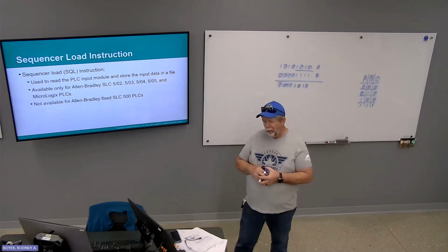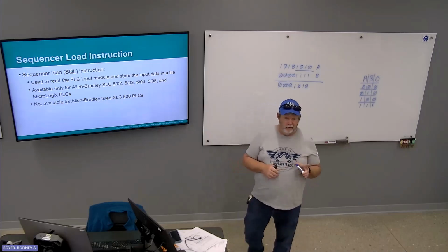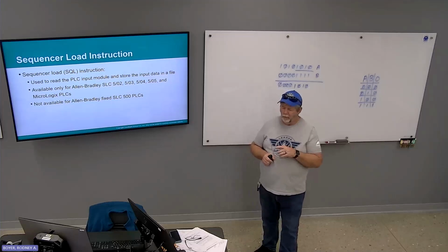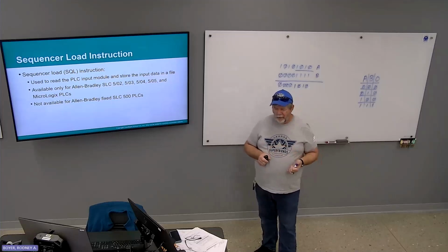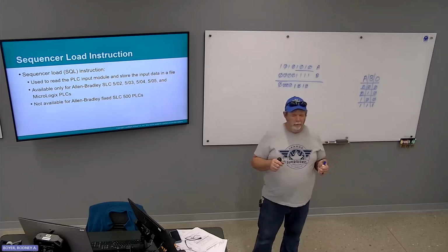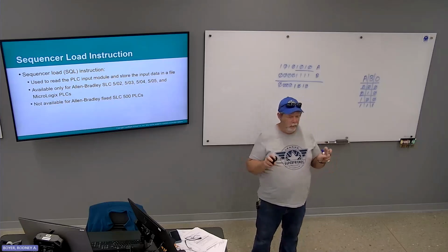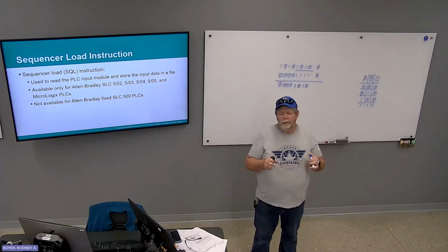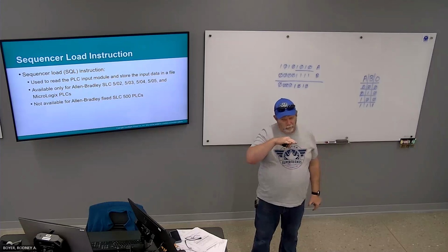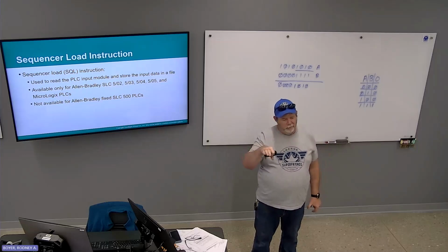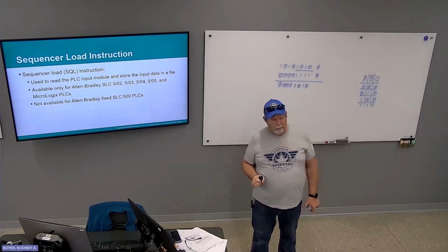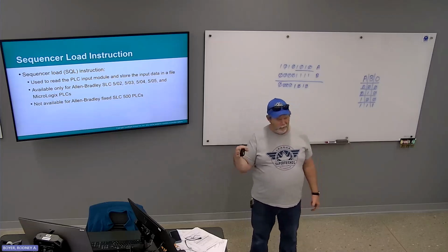Okay, sequencer load, this is one that you can actually sort of make a case for. If you have a system that you're trying to teach, you can say, hey, when these inputs are on, I'm going to record the status of all those inputs into whatever source file, maybe B3:7.